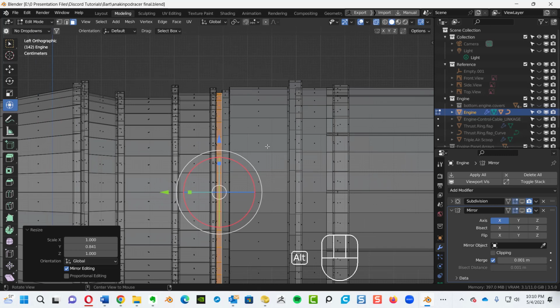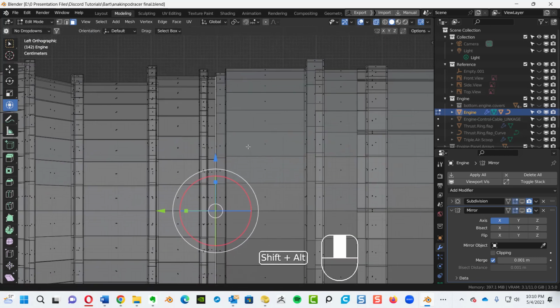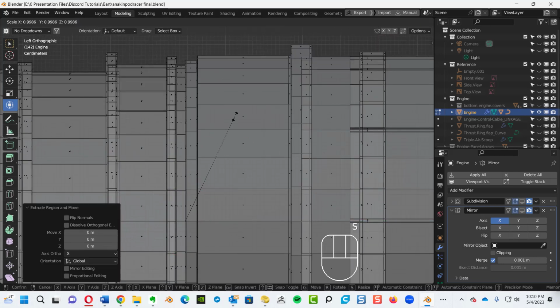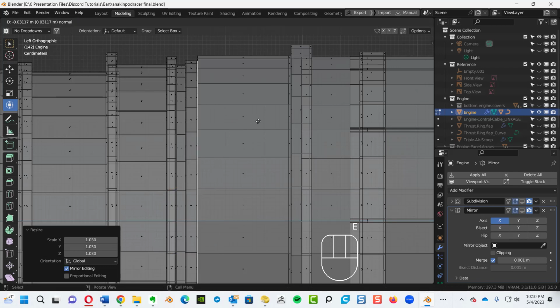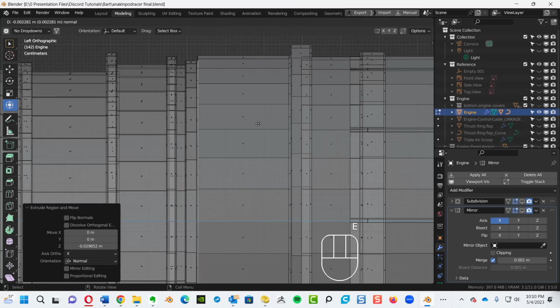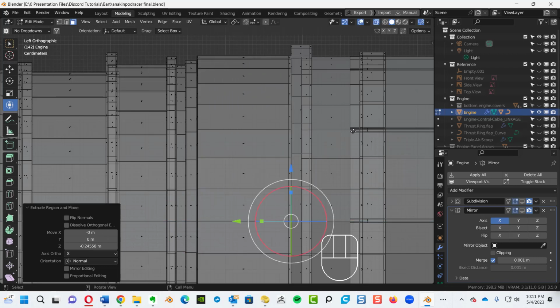All right, now I can deselect the side with Control and just drag and deselect those sides so that only that front face is selected. E key for extrude, S for scale, E for extrude. Okay, I'm going to extrude again. S for scale, pull it on up. E for extrude. E for extrude again, right click to set it back, S for scale. E for extrude.